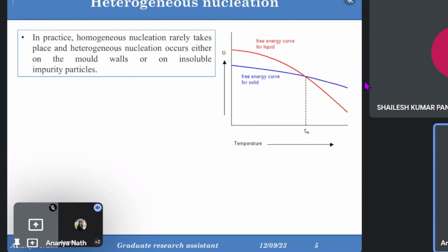And then the growth part is another thing. If we keep that material for a longer time, the nucleus will grow. The lattices will try to get arranged and minimize their mismatch with the other lattice, the other grain, so that they can form a bigger grain. So the growth part is different. We are just talking about the nucleation.